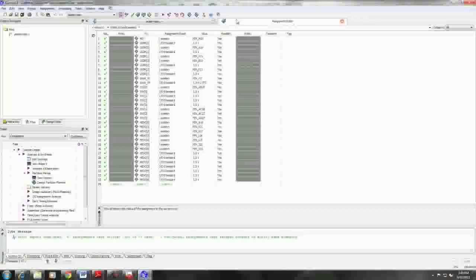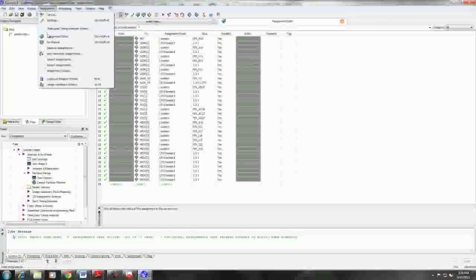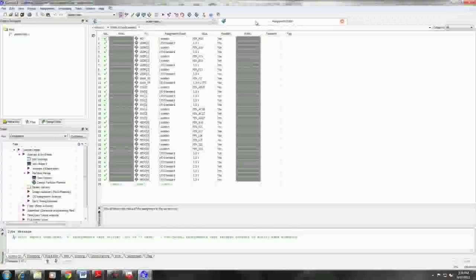So in the future, you can use System Builder to select what hardware you're using, and it'll automatically generate all of your pin assignments. But if you need to do it the long hard way the first time around, this is what you're going to be doing. And for this particular project, you're going to end up with close to 200 pin assignments, because each of the pins that you're using does need two assignments. It does need the input-output standard, and it does also need the location.